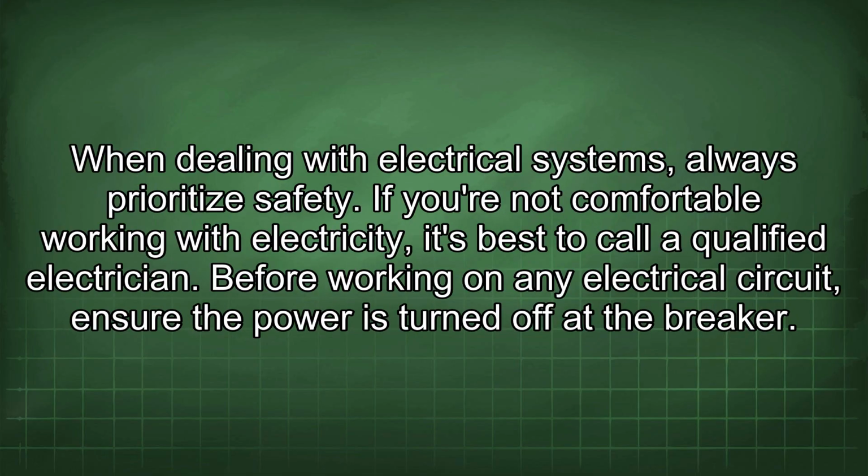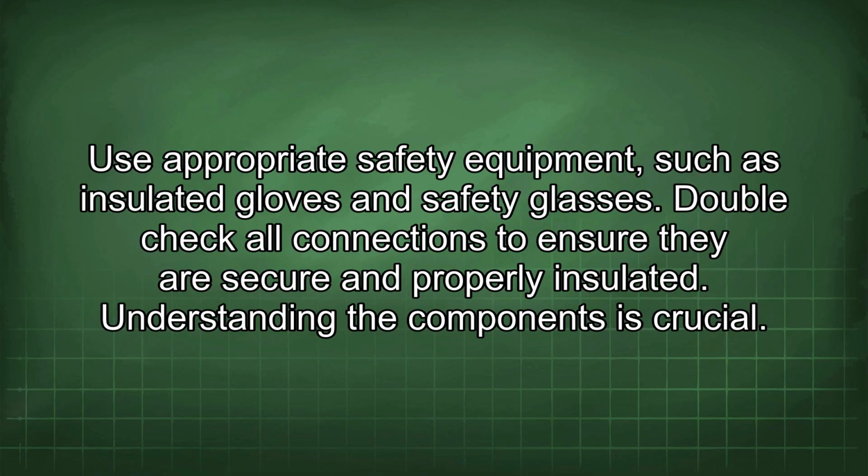When dealing with electrical systems, always prioritize safety. If you're not comfortable working with electricity, it's best to call a qualified electrician. Before working on any electrical circuit, ensure the power is turned off at the breaker. Use appropriate safety equipment, such as insulated gloves and safety glasses. Double-check all connections to ensure they are secure and properly insulated.